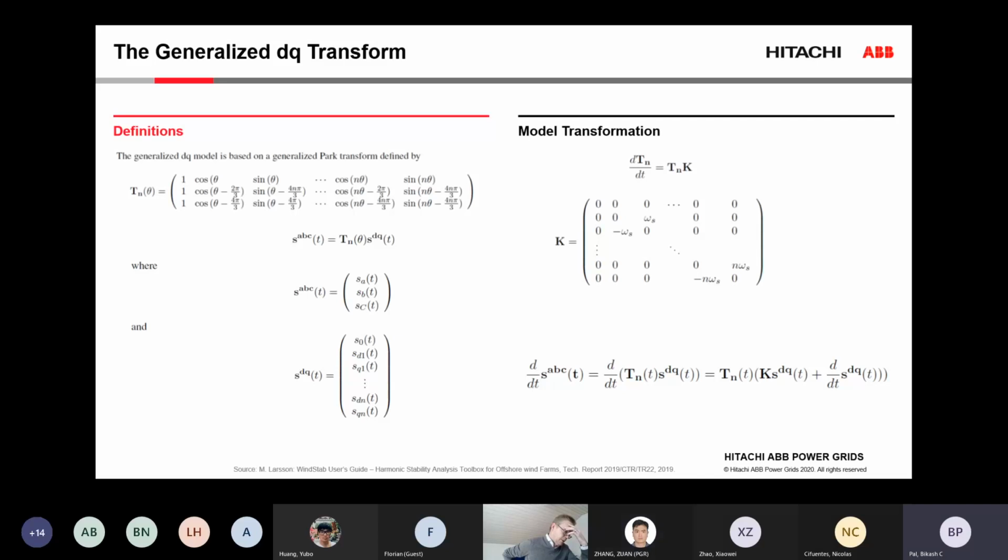Okay. But one interesting problem that comes up is if you have a very large wind farm with, say, 100 copies of the same thing, for example, the current controller in a wind turbine. It means that when you calculate participation factors for the state of that, it will be a very small value because it's only 1 out of 100. You may need to look for ways of grouping the states based on their names and so on to really figure out the importance.